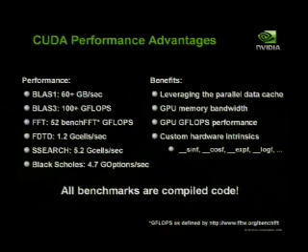I should emphasize, of course, we have more memory bandwidth than a typical CPU because graphics tends to be very sensitive to memory bandwidth performance, so we use the fastest memories and dedicate a lot of our pins to memory. But importantly, we can leverage that parallel data cache. So we can capture some of the gigaflop performance, all those shaders that are in the GPU, by keeping the data close to the ALUs by spinning inside the parallel data cache instead of streaming out to video memory and back.